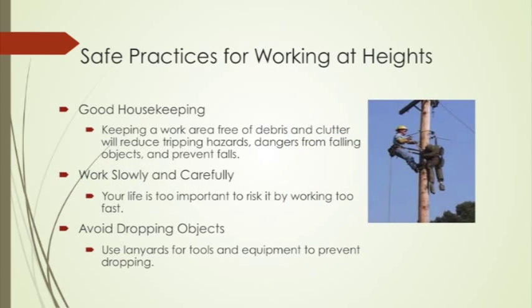Working at heights provides its own dangers. Other dangers that are easier to eliminate include keeping the work area free from debris and clutter. Doing so will reduce trip hazards and dangers from falling objects and help prevent falls. Doing the job right the first time not only saves time, but it could save a life. Too many accidents occur when employees are working too fast.